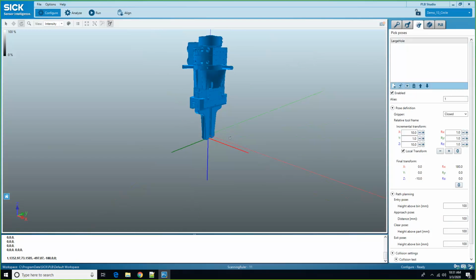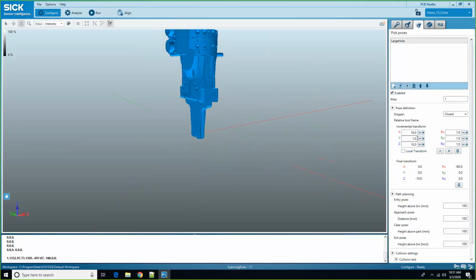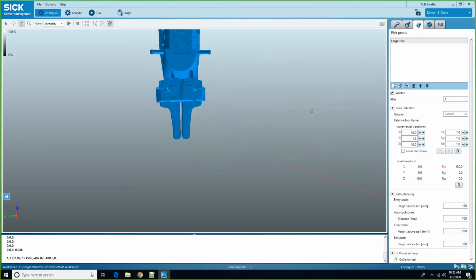So when we do a localization, you'll see a coordinate system pop up. That coordinate system, if I turn off local transform, is associated with the one you see here. If I move this up, you can see this origin here. That's where my coordinate system is when I get a localization. This is what I'm going to be referencing, and so I'm putting my gripper in reference to that localized coordinate system. It'll probably make more sense in a minute here.